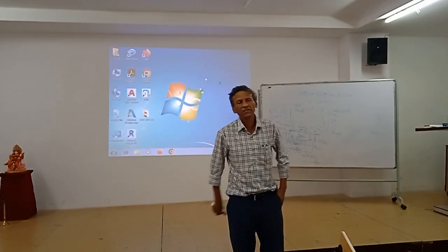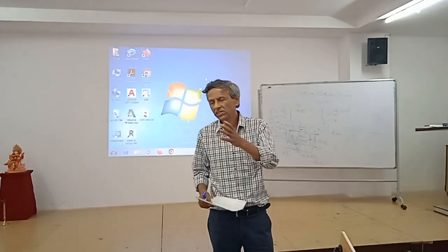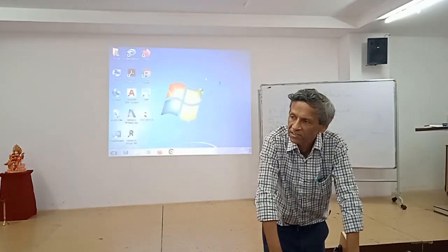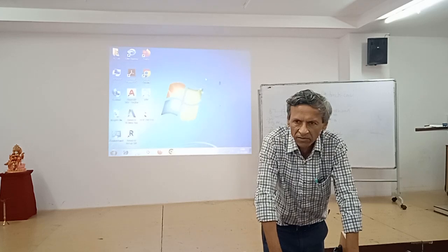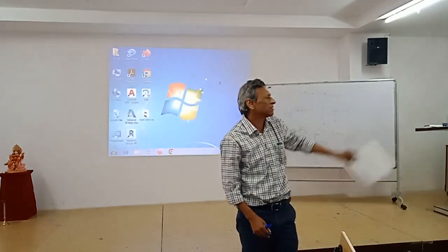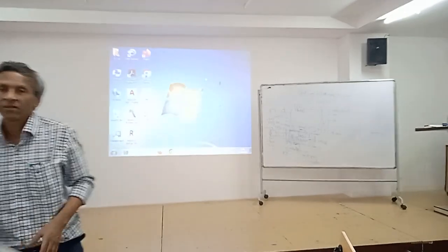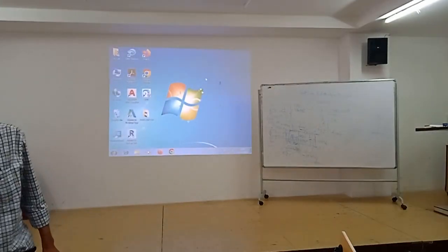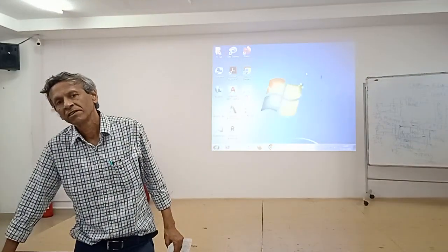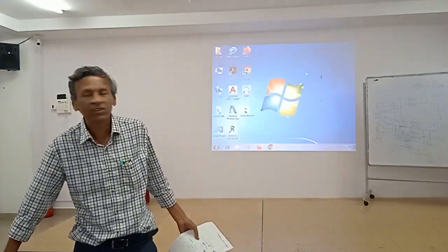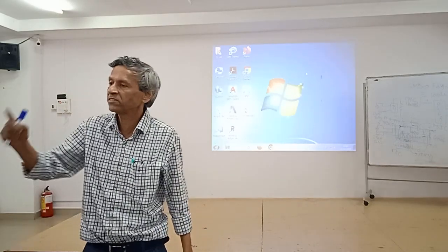In PFC, you have increased the frequency, you are doing PFC at switching frequency, that is your 15 kilohertz. And then suppose I ask you another very interesting question. Somebody would say, sir, let it be 10 kilohertz. And I will insist, no, let it be 15 or 16 kilohertz. Why? Again, a very simple question, but very important. Somebody would say, sir, let it be 11 kilohertz. Again, I will insist, firmly no, let it be 15 or 16 or 17. And then a question, sir, why are you so rigid? I am proposing 12 kilohertz, 11 kilohertz. Still you are sticking to 15, 16. Why?